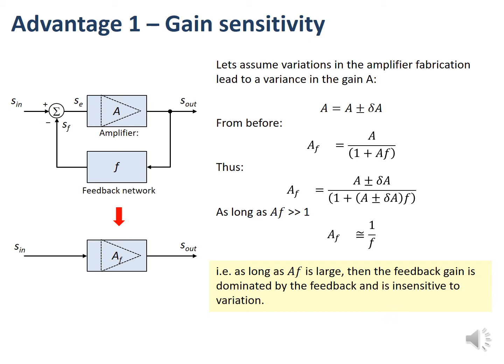The resistors are incredibly reliable in terms of manufacture, and their values are always very precise. Whereas transistor circuits, which is essentially what the op-amp is, do vary. That could lead to unwanted variations in the circuit property. But here I'm pretty safe, because I know that my answers are in terms of the actual reliable resistor device.